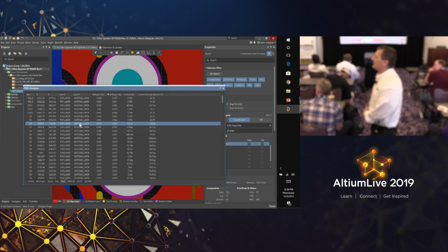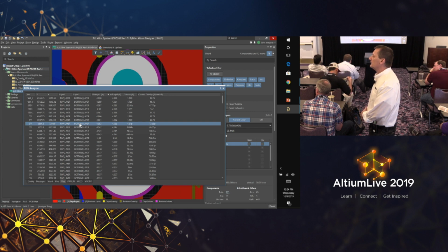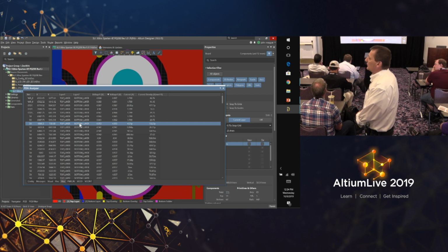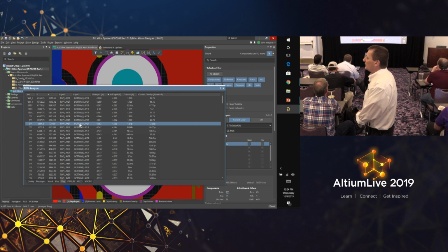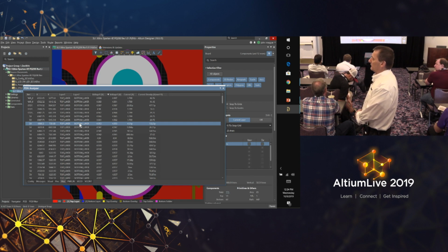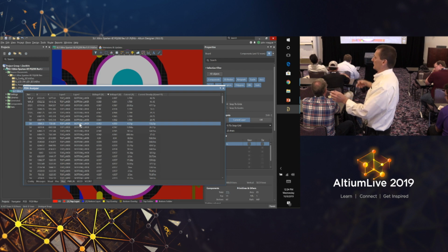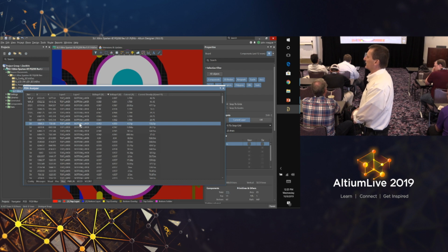Hello. So in the previous example with the via that failed, how are the minimum and maximum settings for the vias set up? Is that a default within Altium, or do you have to click on each via and say, I have a maximum current through this 10 mil via of 200 milliamps or something? So that was estimated with a third-party calculator, so it's not internal to the tool. What it allows you to do is choose the smallest via size and the largest, and you set your smallest constraint and then the largest constraint, and any sizing that falls in between, it'll interpolate from those extremes. So the responsibility is to calculate that yourself and then apply those constraints.